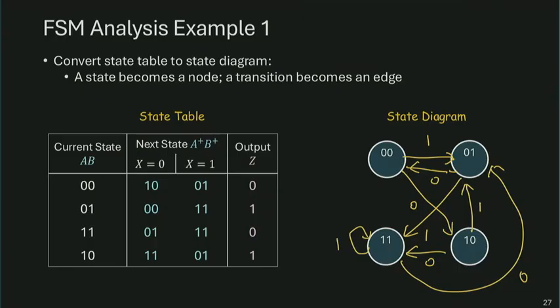On the transitions, I also specified the corresponding input conditions. And this is a Moore machine, and therefore output will be annotated on the states. So under each state representation, we have an output: 0, 0 produces 0, 0, 1 and 1, 0 output is a 1, 1, 1 output is 0. And that is my complete state diagram.